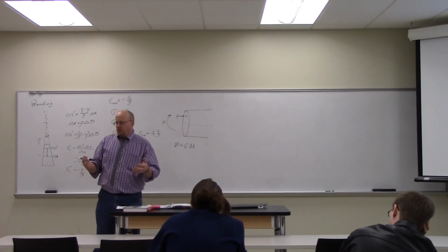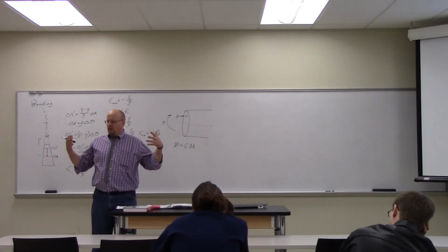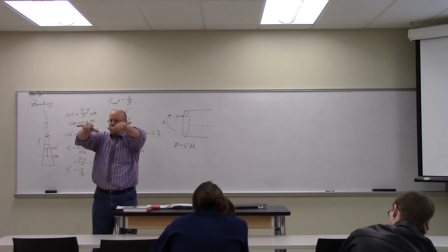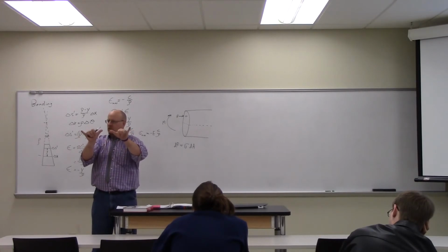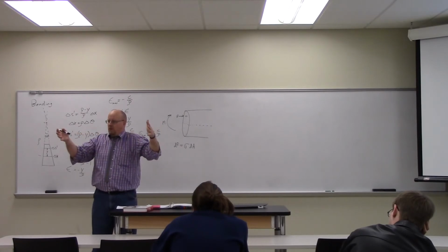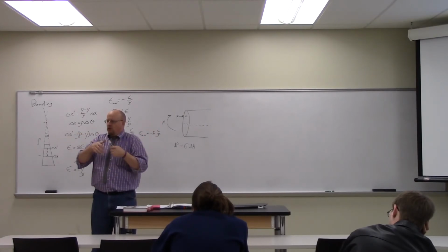But realistically, on a macro structure like this, if I was bending a piece like this, I'd probably handle it in terms of forces rather than in terms of moments, because the separation of my couple is comparable to the dimension of my system. That's why I used a screwdriver as an example.